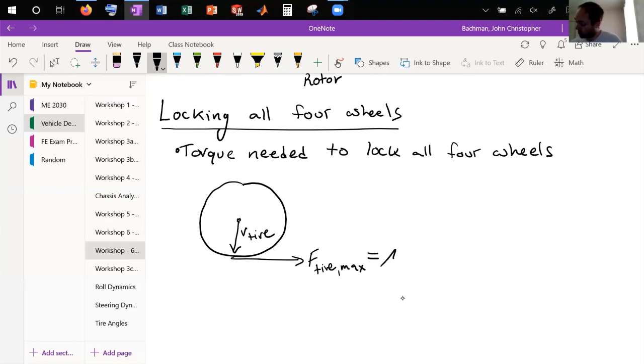And so this is going to be your max coefficient of friction, or more specifically, this normalized longitudinal force, right? Sometimes this is the normalized force in the x direction. Most higher folks will say it's longitudinal. So you have mu max times the normal force. So this mu max, that's just basically friction, right?